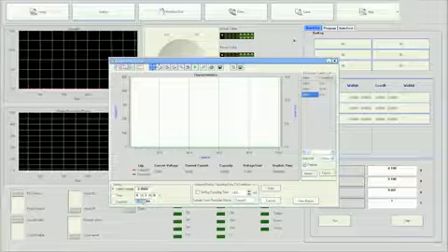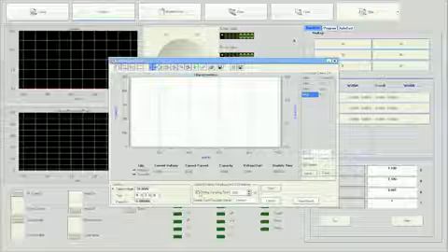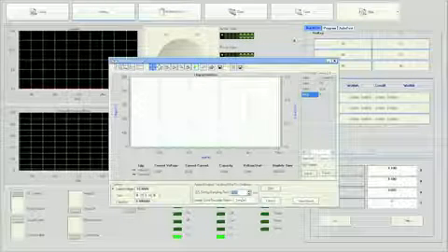For this setup, we will specify to run the test with a safety voltage. Let's enter 10 volts. If data will be recorded, check the box that says Setting Sampling Time and enter a data sampling time. By default, we will leave it at 1000 milliseconds. Users can also change the name of the recorded data. We will leave it as default, sample 1.